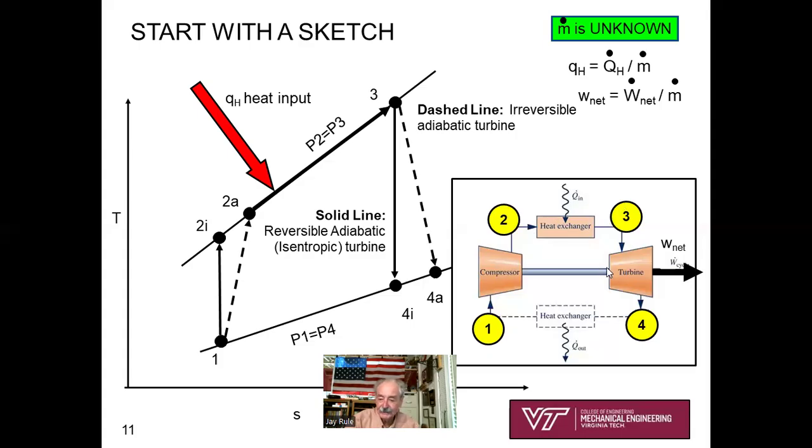Do you see that there's a single shaft coupling the turbine and the compressor? So the turbine is going to put out an amount of work required to drive the compressor, and it's going to put out more work so that we can pull what's left over to, let's say, run an electric generator, little w net. Okay, and so here is our TS diagram.